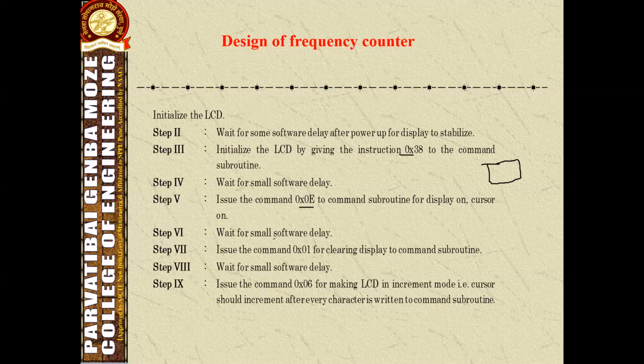Then after that, wait for a small software delay. We have to wait some delay after the cursor is on. Then issue the command 01 to the command subroutine for clearing the display.